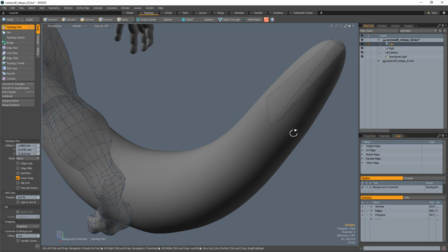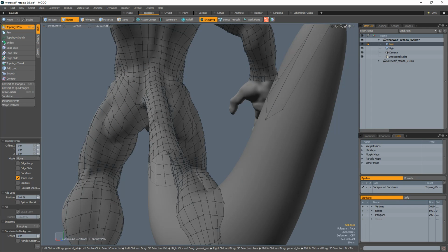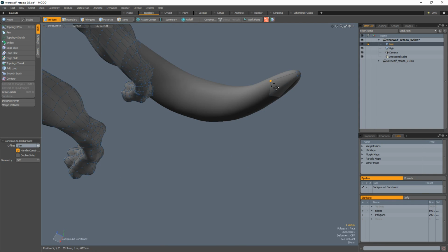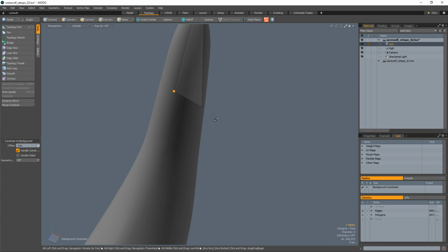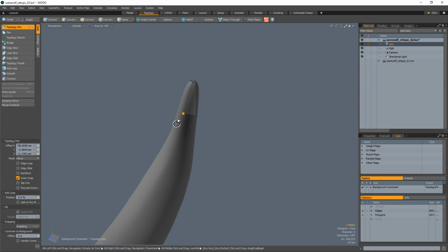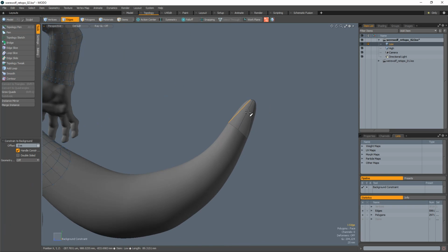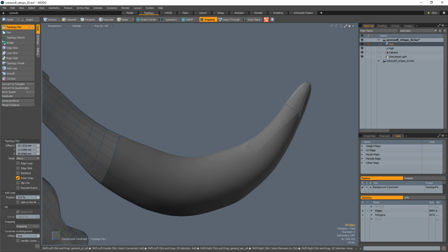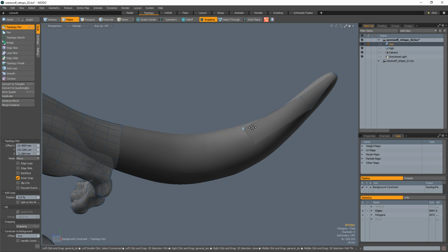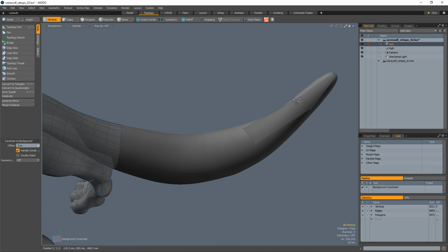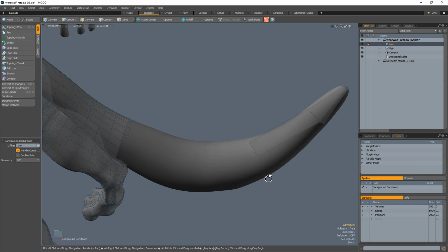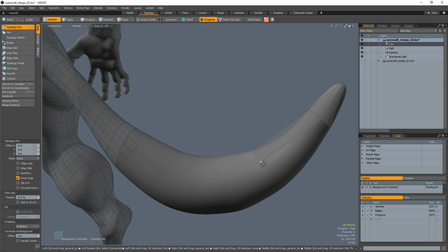So here's the center line for the side. Let's move this to the center line for the bottom. Move this to the center line for the top. Make sure that everything's nice and evenly laid out. Alright, cool. Let's add some more. We're continuing this center line. This right here is the line along which we're going to mirror things. So let's just get that right to the center.